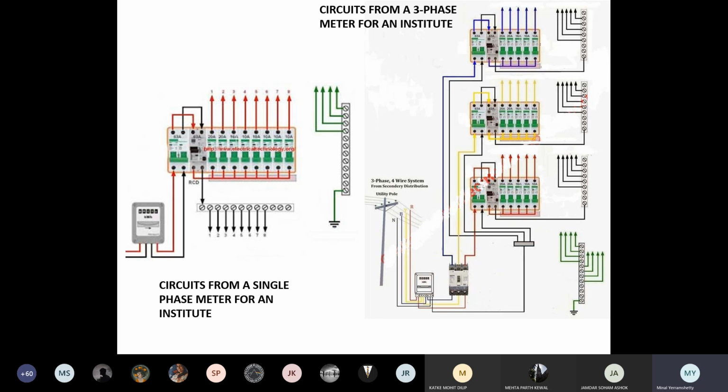What I will do is, now understand this, guys. From the KRVI meter room, I am taking the first line up and putting it towards the toilet area, right in front of the 5th year. There is a toilet and next to it is its electric panel. I will go and put my first bunch of electricity there. From that load, I am distributing. So part of that distribution happens.